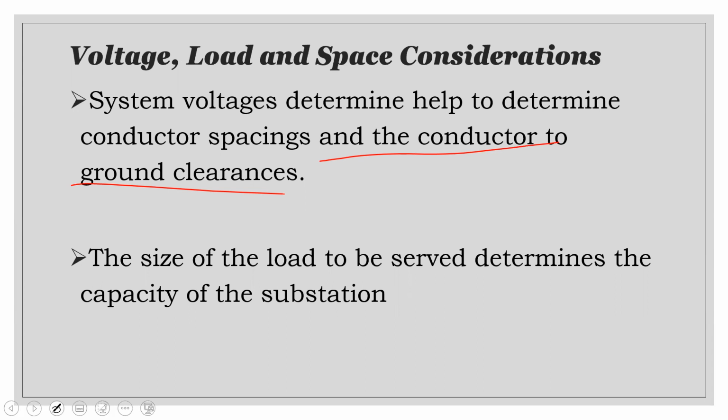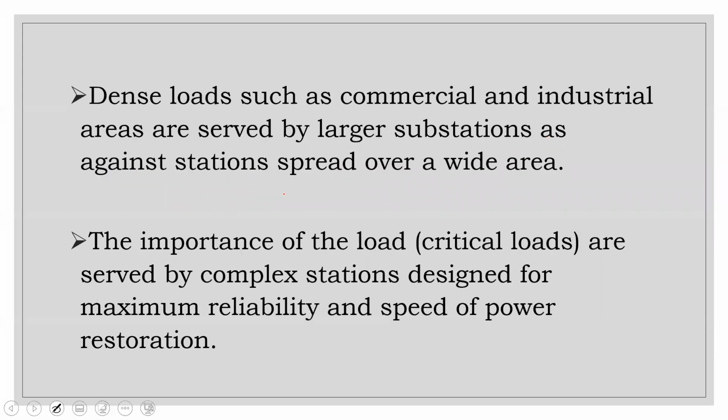Now, the size of the load that needs to be served also determines the capacity of the substation. Right. What is the loading? So you're going to buy your transformer based on that. What kind of load are you doing? Remember I said earlier, and you see, I come back to that beautiful question from Ms. Michael. Because the type of load, whether it's commercial, industrial, or residential, will dictate the sort of substation that I build.